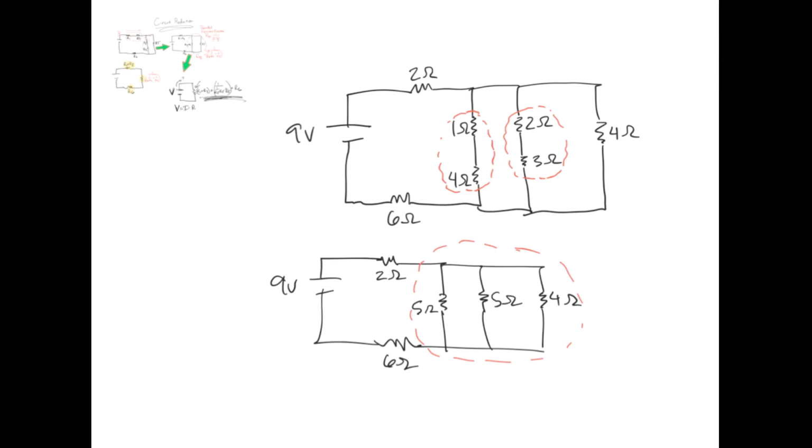So I can do the math of that's all acting like 1 over 5 plus 1 over 5 plus 1 over 4. And I got to look for common denominators. So let's see, 5 and 4, we could do 20. So I'd have 4 20ths plus 4 20ths plus 5 20ths, all inverted. And you got 8 plus 5. The total of that, we're going to have 13 20ths, but we flip it over. So that all of that section is acting like 20 over 13 ohms. So that's what that whole chunk acts like.